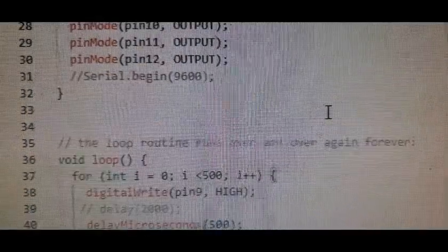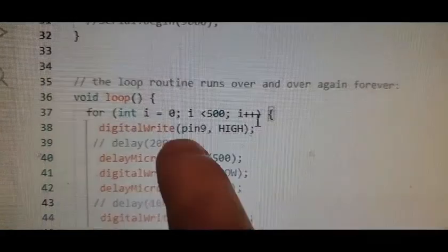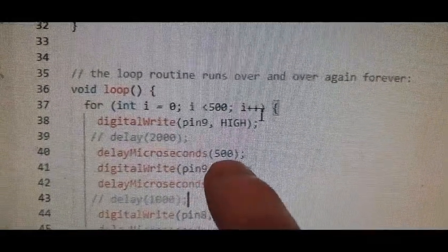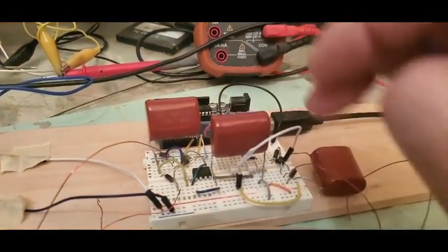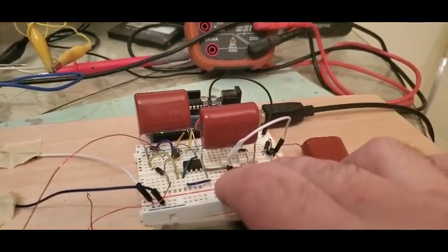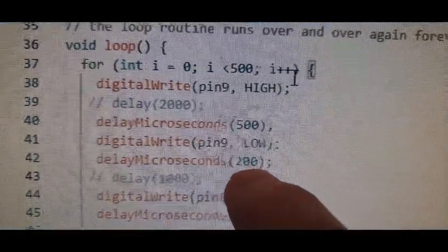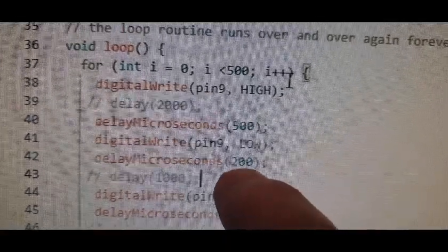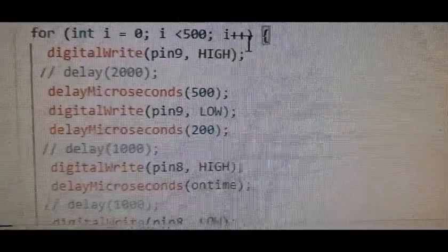And so here we have our for loop. We say pin 9 high, and that's 500 microseconds. Pin 9 is when charge flows into the cap. We make and break the positive and negative lines, as we talked about in the setup for how to make this circuit. And then we just shut those off. I just left it as 200, for a couple reasons, but just make sure it has enough time to shut down, and probably get away with like 50 there.